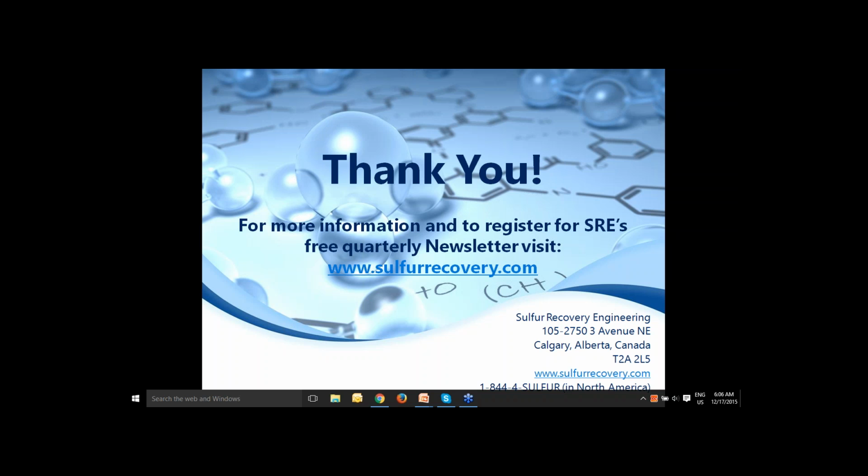It's true. A lot of places will have just an SO2 analyzer, but the best practice operation is a mass-based analyzing system where we measure SO2 emissions and also the mass flow rate through our stack. And if we're able to measure mass flow through our incinerator stack, we can optimize the amount of combustion air that we add to our stack. And through that, we're able to minimize our overall CO2 or greenhouse gas emissions.